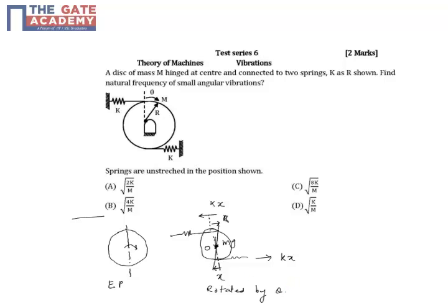At this position, when we have rotated by angle theta, the moment about the center, now remember that just like sigma F is equal to ma, the summation of moments about the center should be I alpha, where I is the mass moment of inertia about the center, into alpha. This is a synonymous equation with F equals ma, but we use this equation when you have a rotational unbalance of forces, or unbalance of moments. Then we can use it to get the angular acceleration. So let's do it in the same way.